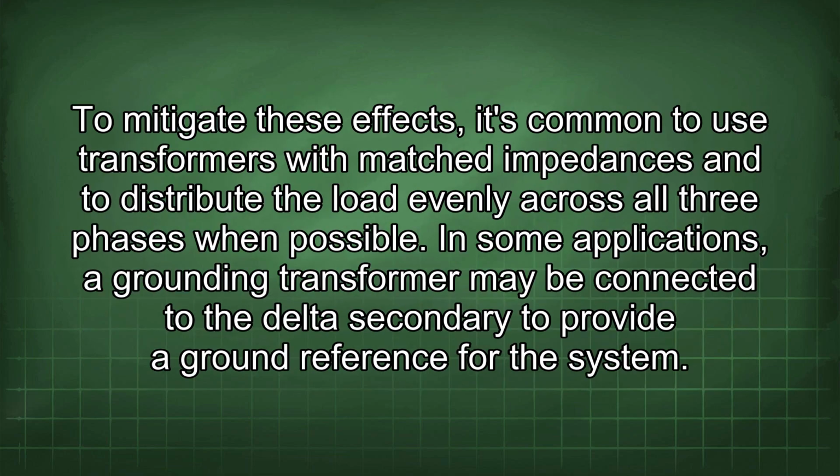To mitigate these effects, it's common to use transformers with matched impedances and to distribute the load evenly across all three phases when possible. In some applications, a grounding transformer may be connected to the delta secondary to provide a ground reference for the system.